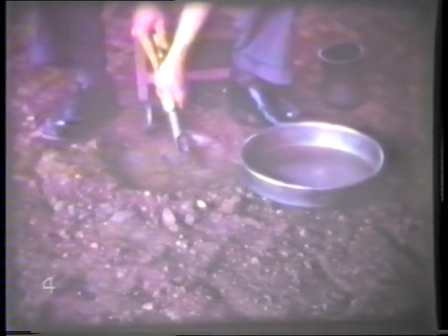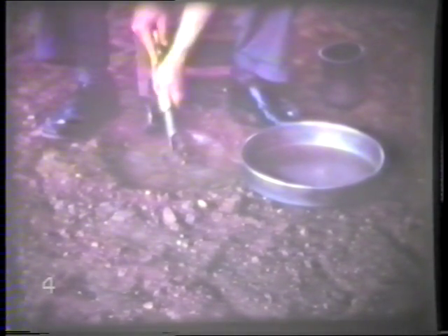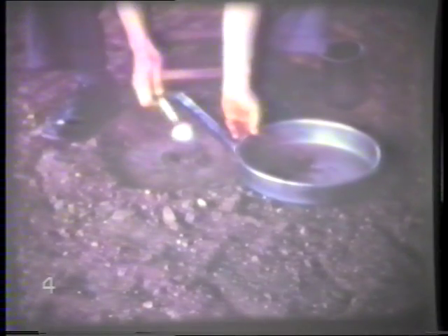The method used for determining the dry density of the soil is the British Standard Sand Replacement Method, which is suitable for all types of soil. After trimming level the surface of the compacted soil, a hole about 4 inches in diameter and 6 inches deep is carefully excavated, all the soil from the hole being collected in a tray.